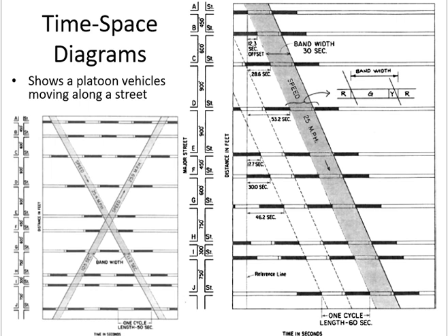The first progression starts with the first signal. So the first progression is the 30 seconds from the first green. The next one will be when the signal becomes green again. After this red, again 30 seconds of bandwidth. Then again yellow, red, and then again 30 seconds of progression. Clear? So every time the first signal becomes green, you have this much bandwidth for the progression of vehicles. Anybody who comes before or after will stop.